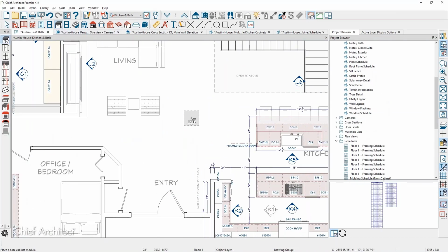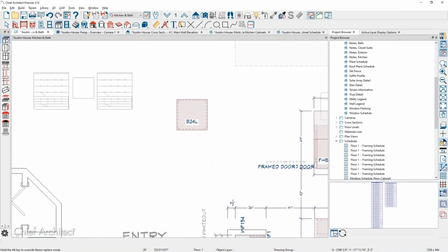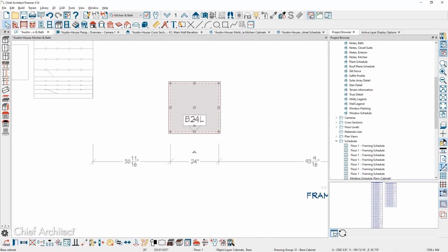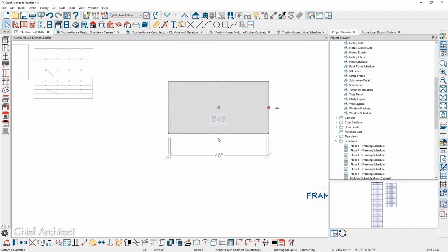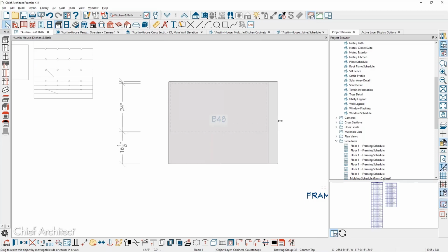So Kareem, I think what I would do is use a custom countertop. When I place a cabinet, let's say this is going to be my sink base, I would separate the countertop using the generate custom countertop. Let's make this a little bit bigger so it's obvious that it's beyond the countertop. And then I would place your sink. Let's assume your sink is some interesting shape.